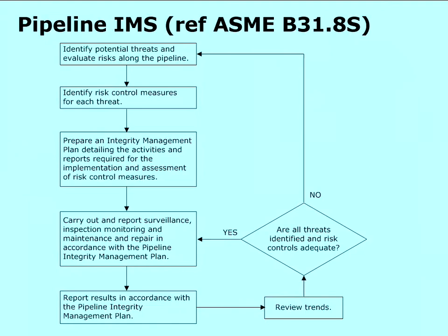Right. There's a lot of interest in reassessment of design life or life extension at the moment, and the reason for this is because pipelines are generally seen as safe. They're long life assets, and so basically at some point you're going to say, well, did they have a design life? Certainly if you considered fatigue or corrosion growth at any point, they will have a design life. And if you still want to operate them at the end of that design life, what do you have to do? So there's a number of procedures involved.